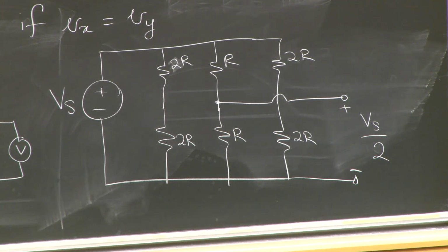But if this is true, that basically tells me if I've got this two-dimensional grid of resistors from before, and I apply a voltage from the top and from the bottom, all I can do is tell which row I'm touching. Right? I can either measure the top one, middle one, or bottom one. I can't actually distinguish between left and right, right? Because of the symmetry in the circuit.